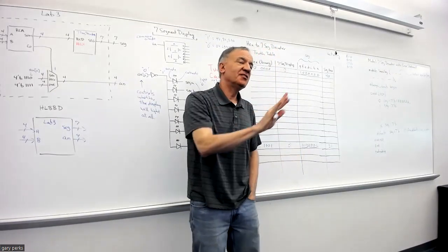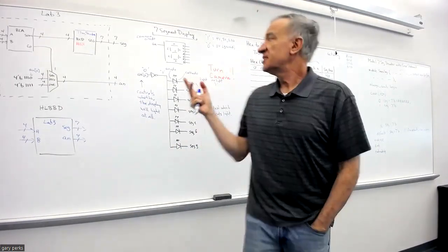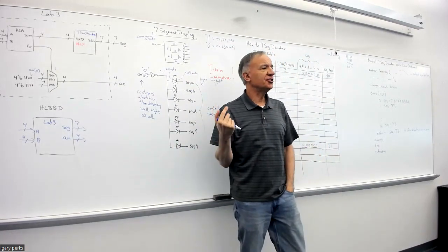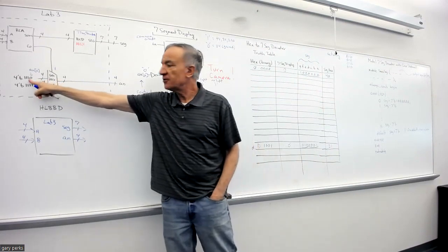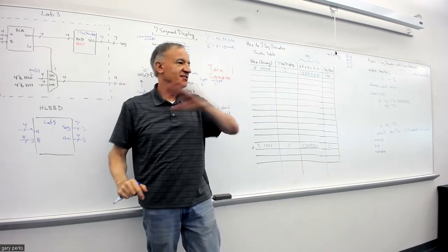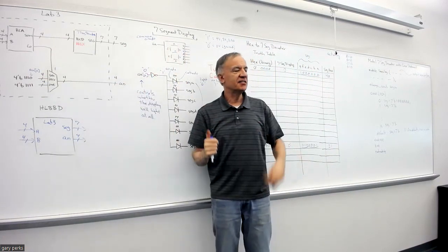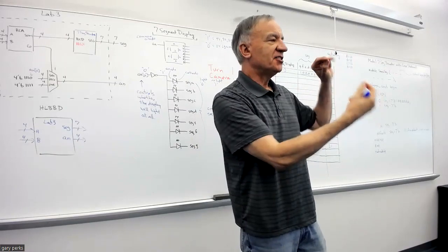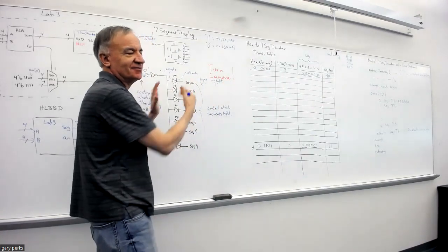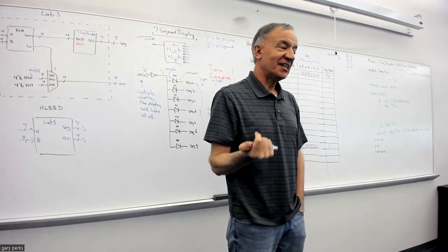I mean, it's a really good question, and we're going to talk about it more in a few weeks because, see, the way these displays are physically connected, they would all show the same data. Like, if you put all zeros here, so all the displays light, and let's say the result is 4, all 4 displays are going to show a 4. Because they're all connected together. In order to get the displays to show different numbers, like if you wanted to show 1, 3, 5, 7 on those 4 displays, you have to use what's called time multiplexing.